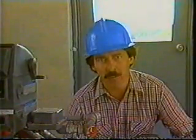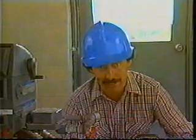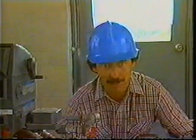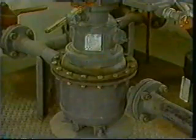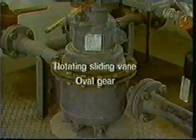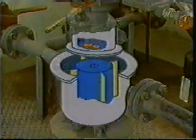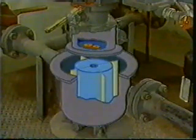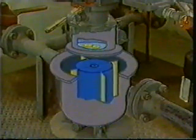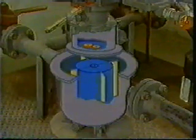There are numerous types of positive displacement meters. They include the piston, rotating disc, rotary sliding vane, oscillating piston, rotary bucket, screw and spiral vane. Commonly used meters are the rotating sliding vane and the oval gear. The positive displacement meter consists of an external housing, an internal measuring unit, and a counter drive train. Let's look at each of these in more detail.